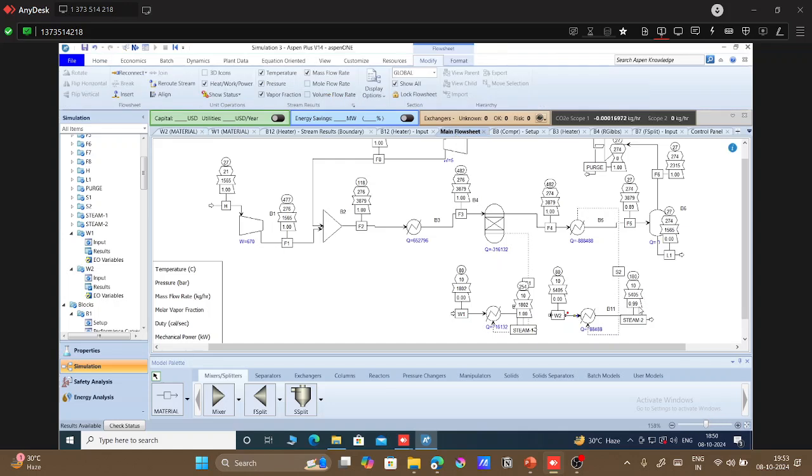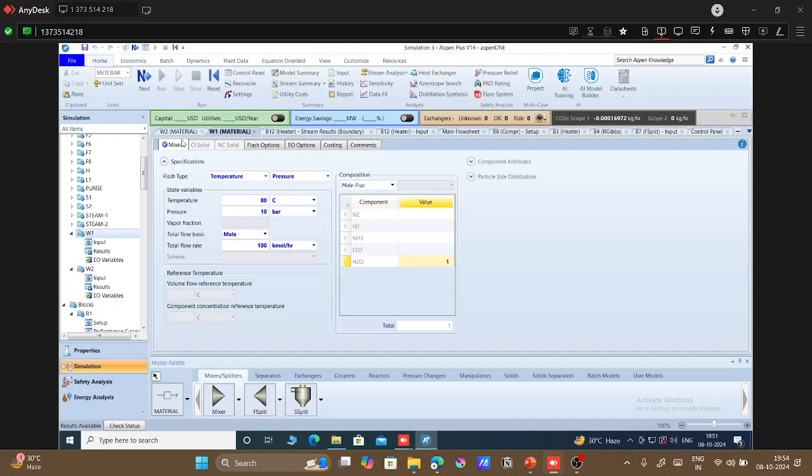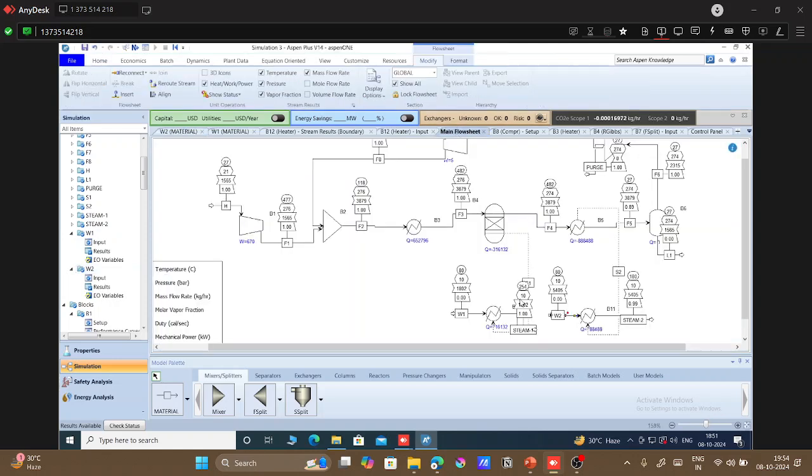So we have 0.99, so almost one vapor fraction, like steam generation has been completed, like complete conversion of liquid to vapor has happened, while the temperature is also below the outlet of the hot fluid, which is 274. Okay, so this is some acceptable amount. So with this heat integration, what we have done, we have generated a total of 100 plus 300, total of 400 kilomole per hour steam at 10 bar and temperature value of 254 and 180 degrees centigrade.